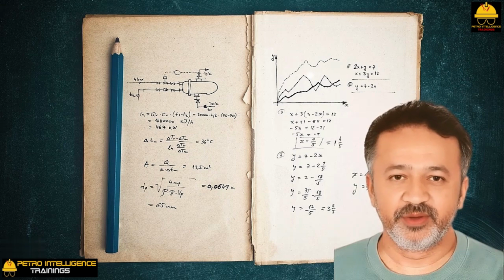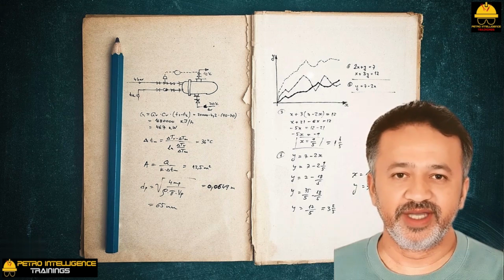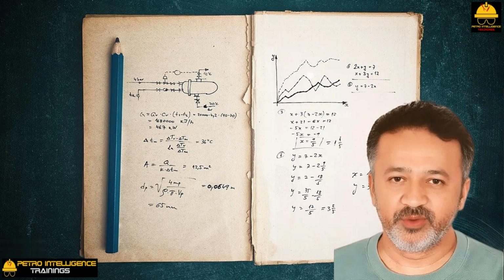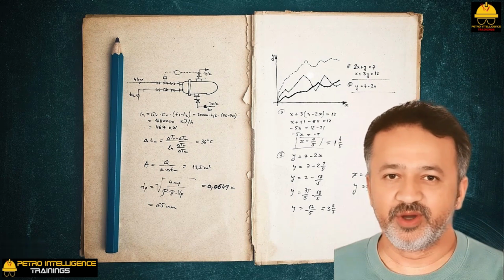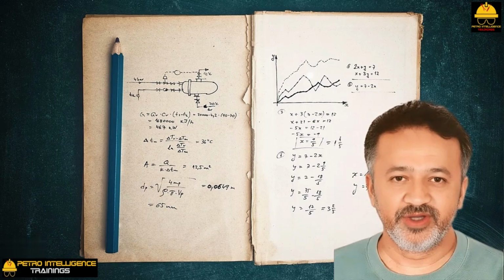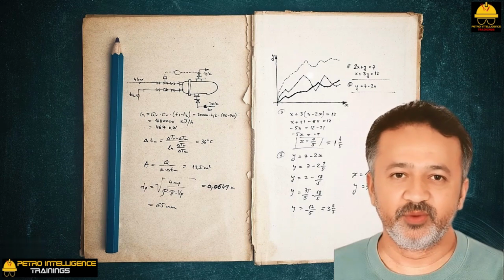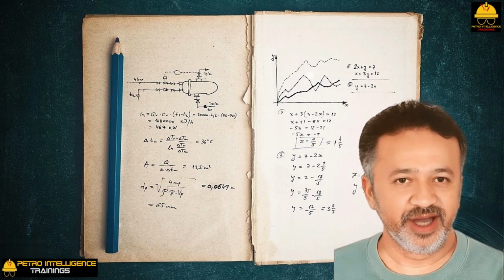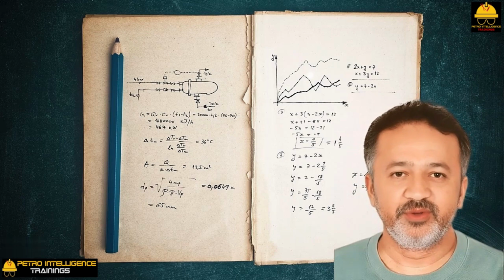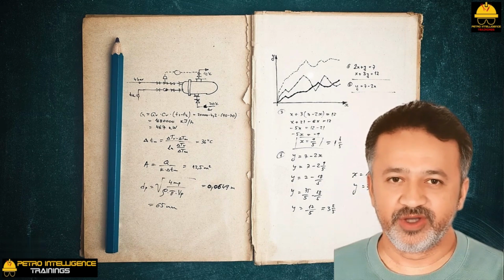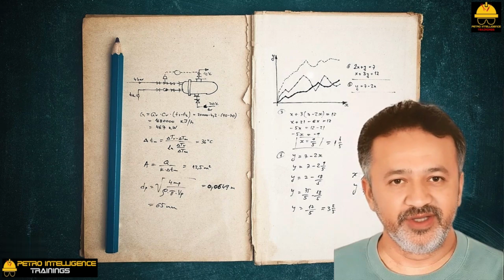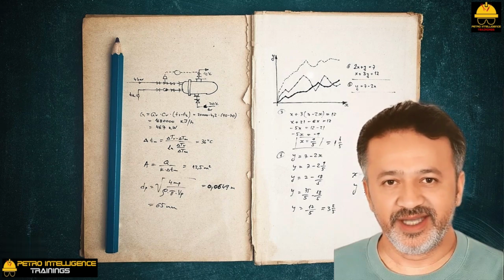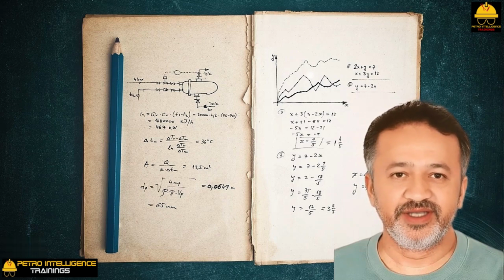A hydroelectric power station generating electricity from a waterfall requires the flow from an entire river. A coal-fired power station generating electricity from steam requires a small water rate that could flow through a 12-inch pipe. The hydroelectric station is only using the potential energy of the water that has been converted to velocity. The thermal power station is using the heat content of the steam that has been converted to velocity.